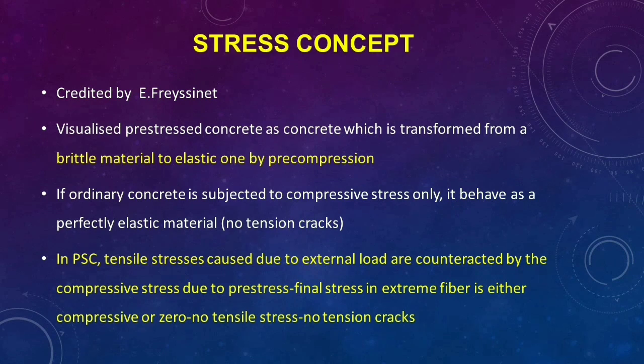Stress concept. This concept is credited to E. Freyssinet, who visualized prestressed concrete as essentially concrete which is transformed from a brittle material into an elastic one by pre-compression given to it. If an ordinary concrete is subjected to only compressive stresses, it behaves as a perfect elastic material because no tension cracks are there. But if it is subjected to flexural stresses, some portion of it will be in tension, resulting in tension cracks. The material under such circumstances no longer remains elastic.